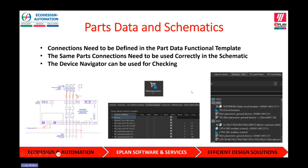When this is represented in your schematic, you can inspect a device under your device inspector, and it will have a couple of different symbols. This white square represents something that's actually placed physically on your schematic. This blue triangle represents something that's actually defined in the functional template. So here we can see a circuit breaker's been defined in the functional template, but a triple circuit breaker has actually been placed in the schematic.